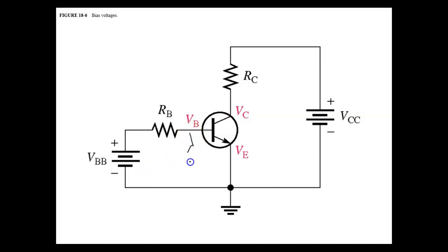This voltage right here, when we measure this, we'll call this VB. This voltage here is going to be 0 because we have nothing. But a voltage measurement between the emitter and common, we call this VE. And the voltage measurement between the collector and common, we call this VC. If we had an emitter power supply, it would be called VEE. So with your power supplies, you just repeat the same letter, right? Everybody okay? Any questions there?